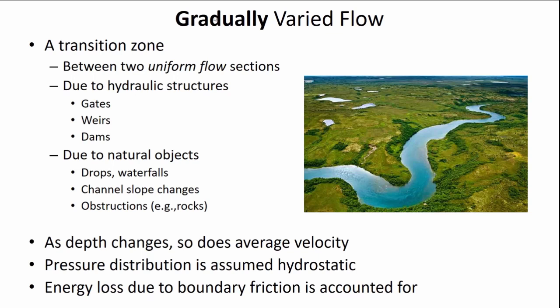When the depth changes, the velocity does as well to maintain the continuity relationship. Now in the calculations we're going to do, we'll assume the hydrostatic pressure distribution as we go down through the depth of the water. And since the water is open to the atmosphere and is moving relatively slowly in open channels, that's an okay assumption for us to make. It's not so bad.